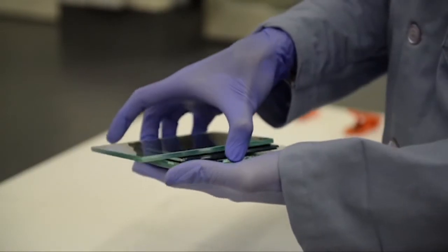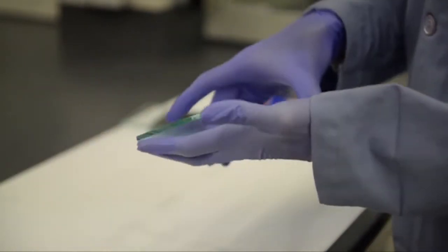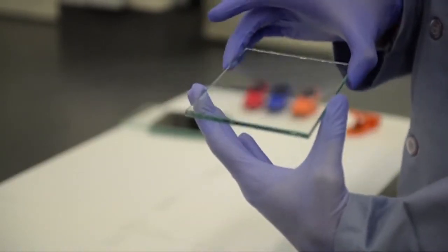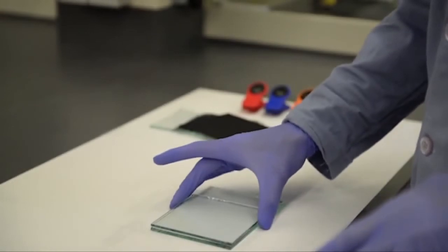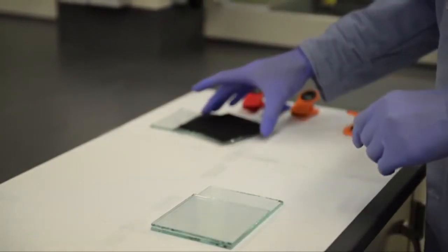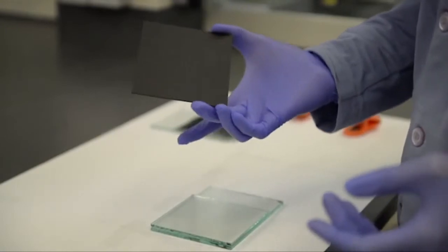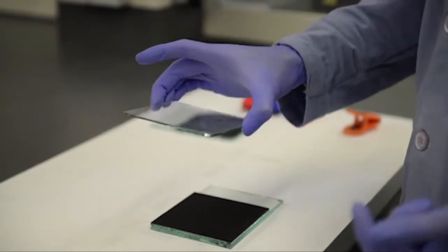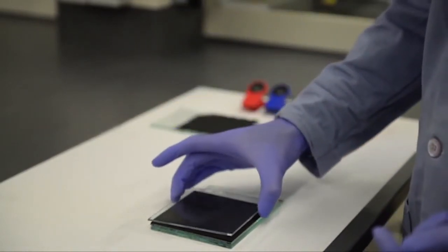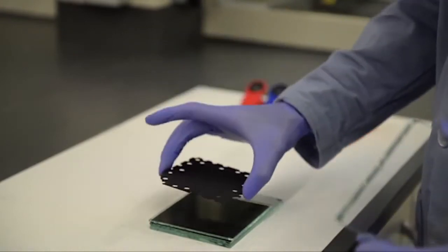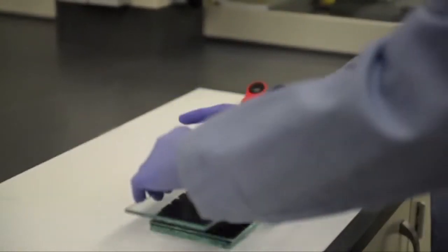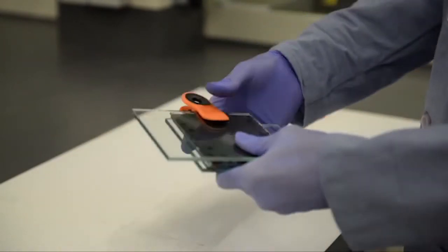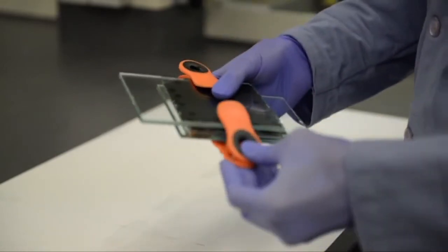First, we are going to use a model to demonstrate the fabrication of the solar cell. We start by placing an FTO glass with the conductive side facing up. Next, we deposit a layer of titania covering 3/4 of the surface. Then we coat the surface with perovskite light absorbing material followed by a layer of copper thiocyanate. To complete the device, we sprinkle carbon particles on the layer and close it with another piece of FTO glass with the conductive side facing down. We use binder clips to hold the device together.